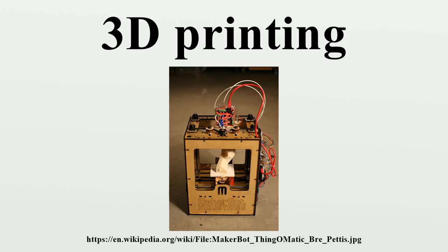Printing. Before printing a 3D model from an STL file, it must first be examined for errors. In fact, most CAD software produces errors in the STL files: holes, faces, normals, self-intersections, noise shells or manifold errors. This step is called repair, as the original model needs to be fixed. Generally, STLs that have been produced from a model obtained through 3D scanning often have more of these errors. This is due to how 3D scanning works, as it's often point-to-point acquisition. Reconstruction will include errors in most cases.